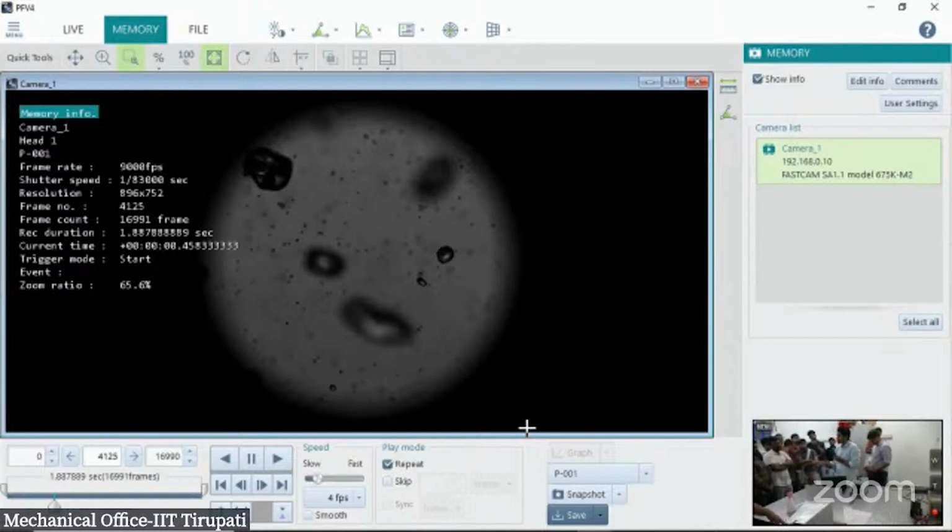I will explain what we generally do to get the drop sizes. It is basically image processing only. We take a background, and from the background we subtract it. Whatever object is in front, we get; otherwise all the background is subtracted. So we get information like a white or black region, based upon our subtraction. From that white or dark area, finally, we get the size of the drop area. So first we have to take the background.